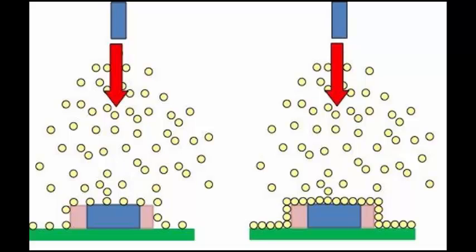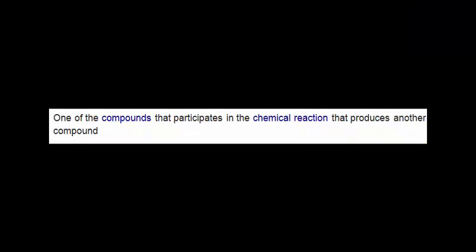In atomized spray coating, the films produced are usually quite thin, and it provides the required thickness of the conformal coating. And the process of layer building also improves edge coverage, since the subsequent layers have a greater affinity for the previously applied layer.